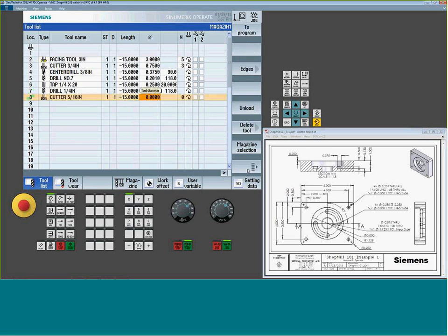Now in these fields, maybe you don't remember right off the top of your head what the diameter equivalent of a 5/16 tool is. You can do basic math, so I can put a fraction in, and it'll calculate it for me. Again, number of flutes, especially if I want to program feed per tooth, that's a must. If I'm programming inches per minute with straight RPM, then it's not going to need the number of teeth. I'm certainly going to want to give it the diameter, because for our cutter compensation, it's going to need to know it.